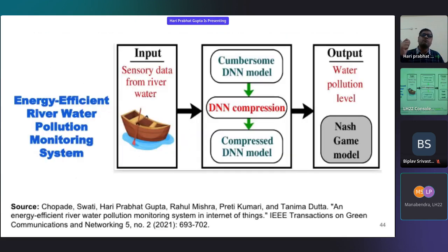Now, if we measure the water quality index with the help of sensory data and lab data, how do we share this information with the end users? For example, in Varanasi, various tourists come and want to identify which ghat is less polluted and suitable for bathing purposes. So they want to see the water quality index. Here we use the complete IoT concept to do this exercise: collect the sensor data, identify the water quality index, and use some communication protocol to share this information with the end user.